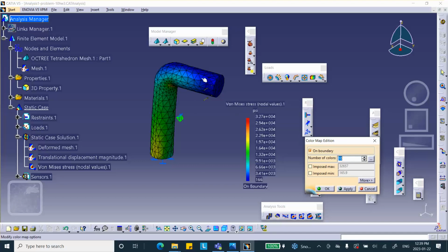But I thought that you could change this thing, instead of smooth color changes, to abrupt color changes. So I thought it was here, but let me see one more time. Oh, yeah, let me click on this. Ah, there. Okay, cancel. You click on these three dots, and instead of smooth, you uncheck it, say okay, and apply. Notice that the colors change here so that there are abrupt color changes, and over here too.